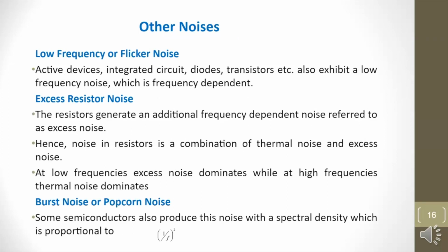Other noises include low frequency or flicker noise, excess resistor noise, burst noise, or popcorn noise. Active devices, integrated circuits, diodes, transistors, etc. also exhibit a low frequency noise which is frequency dependent. Excess resistor noise: resistors generate an additional frequency dependent noise referred to as excess noise. Hence, noise in resistors is a combination of thermal noise and excess noise. At low frequencies, excess noise dominates, while at high frequencies, thermal noise dominates.